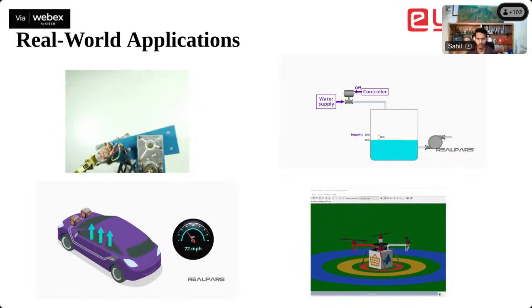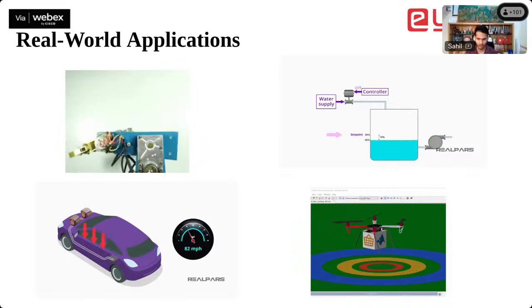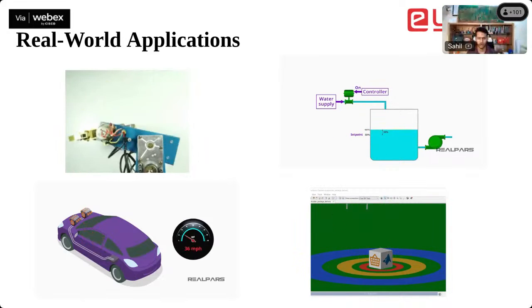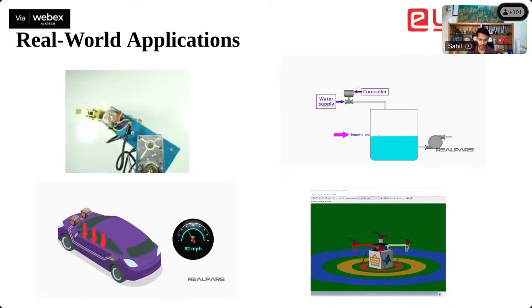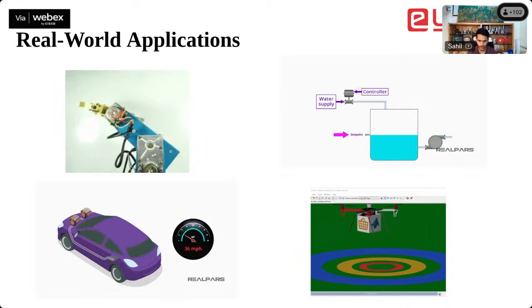Most of the applications use PID. So far we talked about PID as a concept, but let's now talk about how PID works in real digital systems like Arduino, Raspberry Pi, or industrial controllers. In theory, controllers work continuously, but in practice, we work with digital systems that take samples. They read the sensor values at regular intervals.